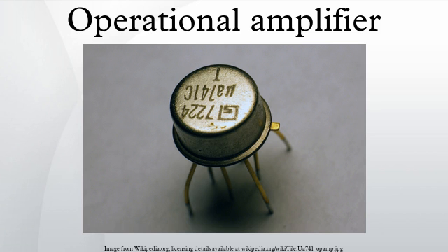A resistor is often inserted between the non-inverting input and ground, reducing the input offset voltage due to different voltage drops due to bias current, and may reduce distortion in some op-amps. A DC blocking capacitor may be inserted in series with the input resistor when a frequency response down to DC is not needed and any DC voltage on the inputs is unwanted. That is, the capacitive component of the input's impedance inserts a DC zero and a low-frequency pole that gives the circuit a bandpass or high-pass characteristic.